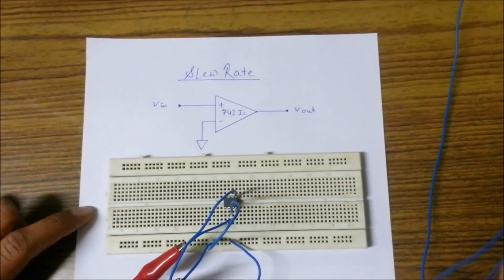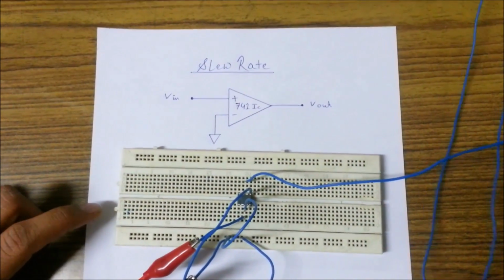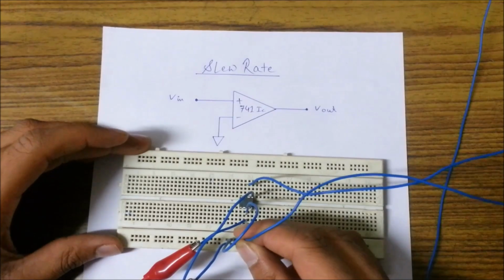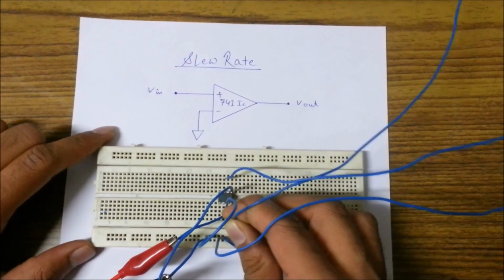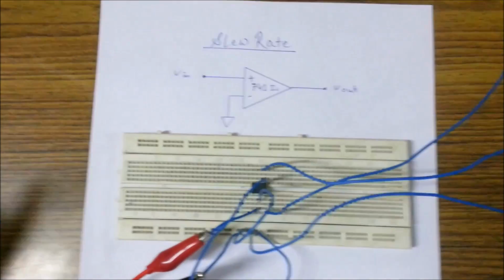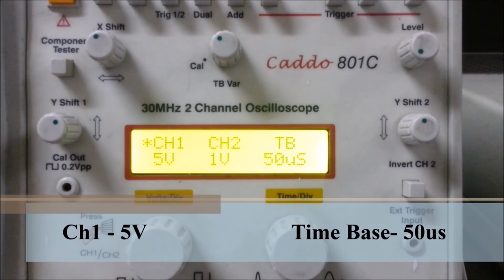Now it's time to apply plus 15 volts to pin number 7 of the 741 IC, setting up the ground connections and applying minus 15 volts to pin number 4, that is minus VEE. Note down that channel 1 is at 5 volt and time base is 50 microseconds.